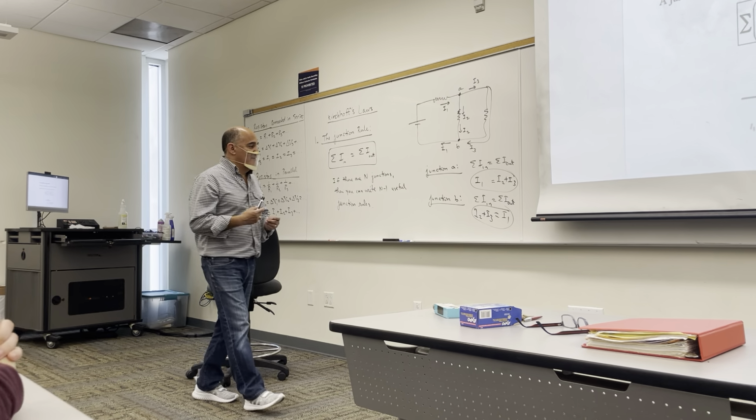I mean, let me show you some problems in chapter 26. Some of the problems for which I wrote down solutions. See, this circuit over here, like that one, right? Let's just look at that one. It's easy to see that these 2 are in parallel, and these 2 are in parallel, and then those 2 combinations will combine in series.